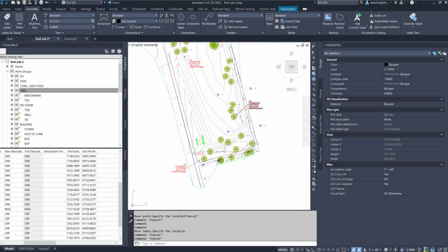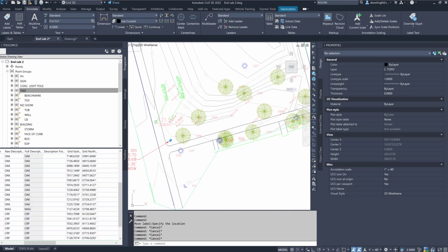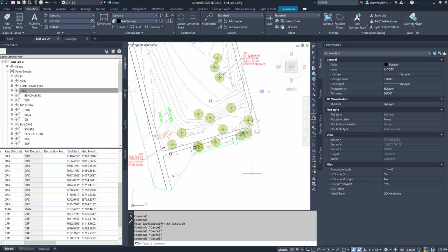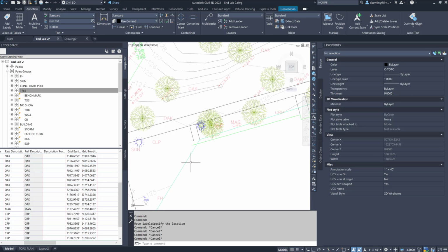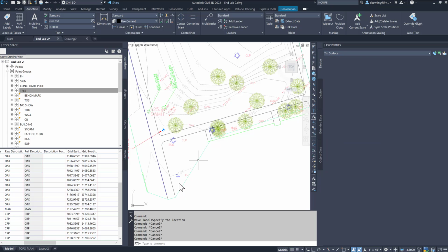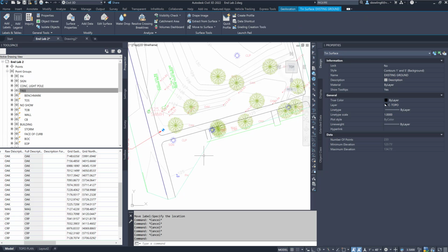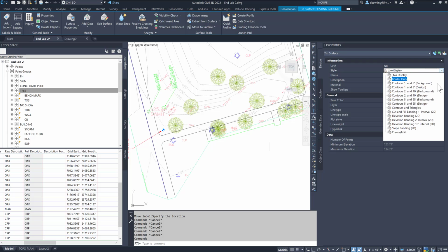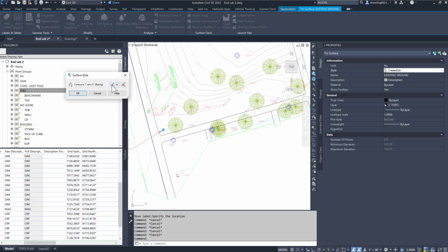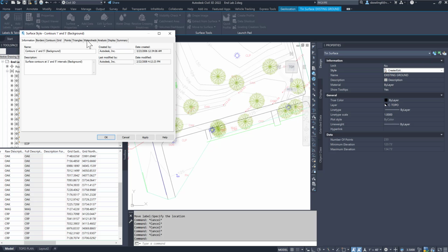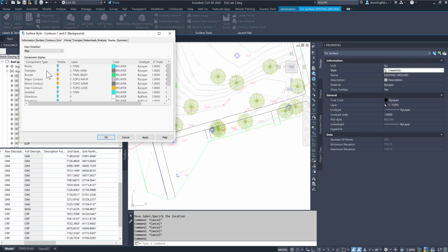So that's a nice thing for the engineers to use to figure out elevations. So just regular text. Before I get on to that, sidetrack, I see something that bothers me. See how this is a green line around our contours? I don't like that. That's a display symbol. If you look at the existing ground and pull it down, you have the ability to create and edit. I'm going to click here and see the little paintbrush and little pencil. If I click that, that means I can edit it. What I want to edit is the display. I want to turn off the border, okay?